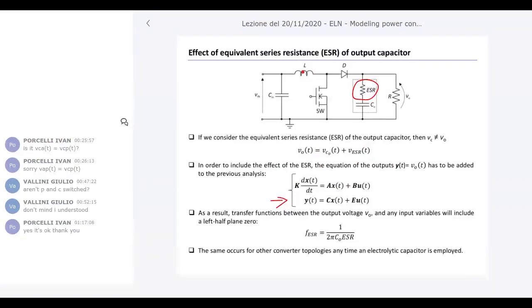In that situation, once you apply the state space averaging technique for deriving the small signal model of our power converter, you have to tackle matrices of fourth order, 4 rows and 4 columns. So it can be a lot of computation.